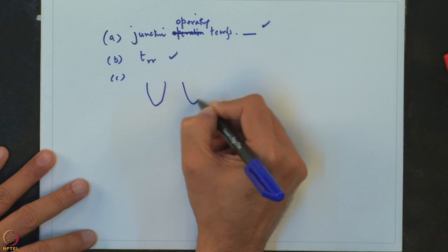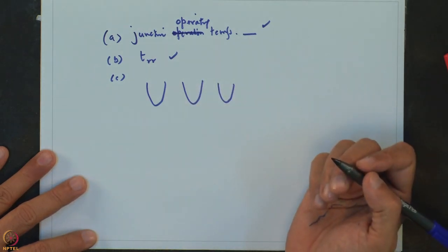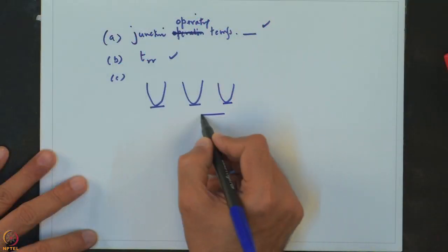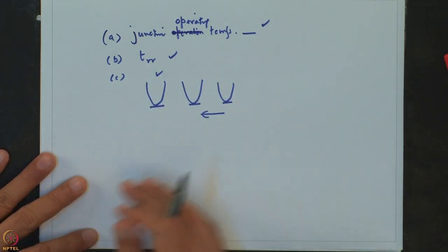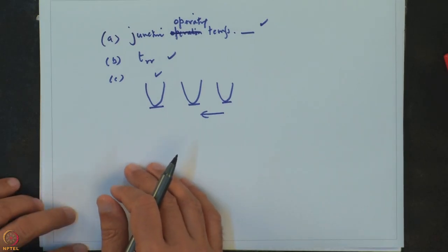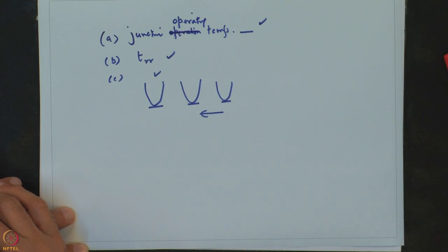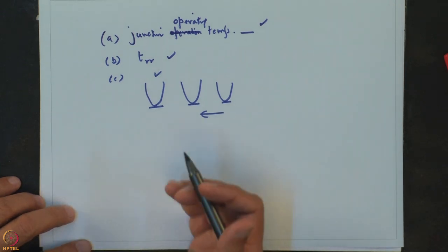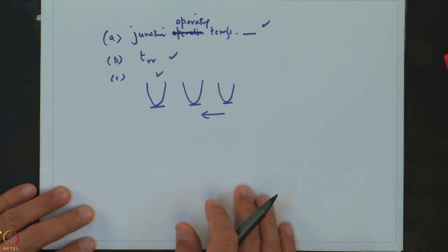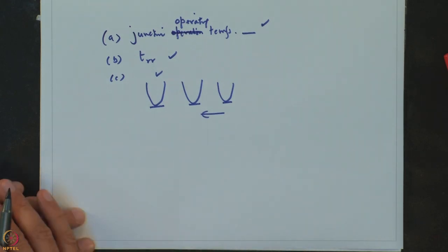For example, in rectifiers, you have these reverse voltages which are going to come across the device when it is reverse biased. So, what are these peak voltages which repeatedly appear across the device? This is again a very important parameter, and it is also important to see what is the one time maximum reverse voltage that will appear across the device. Then, what is the peak forward surge current in the forward direction, what is the maximum surge current that is allowed, what is the average current the diode will allow to flow, what is the RMS current that it will allow, what is the peak current that it will allow.